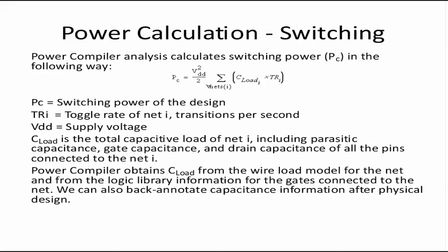This can be either, if we are working at the pre-layout stage, that means we are working on a synthesis database, synthesis netlist, it will be an estimate. We can also use Power Compiler. We can read the accurate capacitance information after the layout has been done. It is called a post-layout database. We can also do